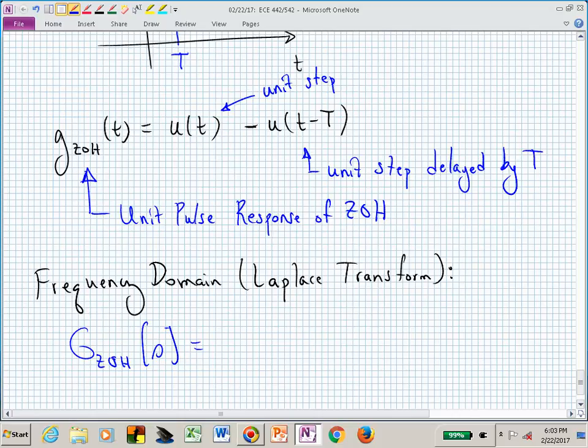Or what is u(t)? As a waveform, that's just a constant waveform, isn't it? And what's the Laplace transform of a constant with magnitude 1? 1 over s, right? That's a signal that's different from an operator. If this 1 over s was corresponding to an operation in the time domain, what would the operation be?